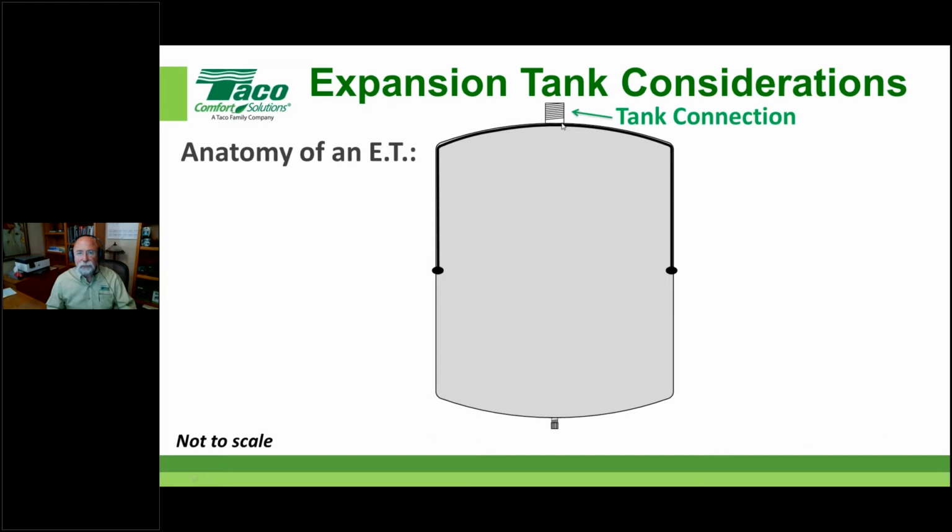Where this actually meets the tank is the least noble portion of an expansion tank. And that's not to say anything to degrade it or derate it or anything. It's just that most of you that have been in this business and done any service work at all know, when you see an expansion tank fail, it's normally right up here at this welding spot. So that's why I say that's the least noble. And we'll talk about some of the ways these should be hung as well. So you'll see maybe extend the life expectancy at that point as well.